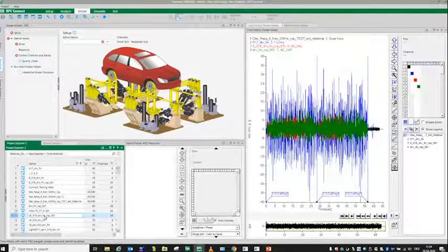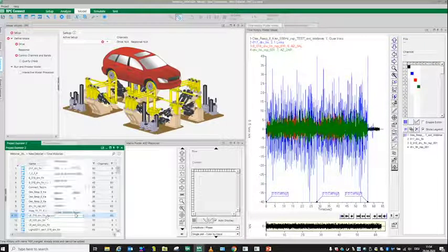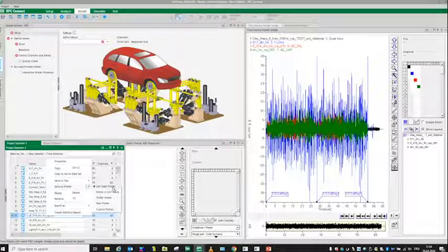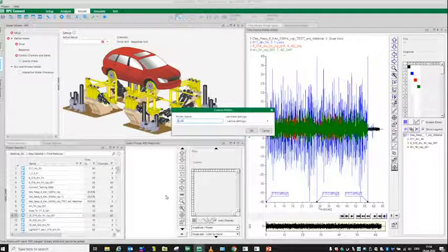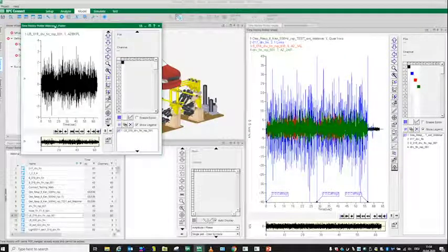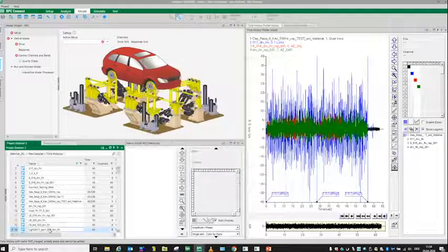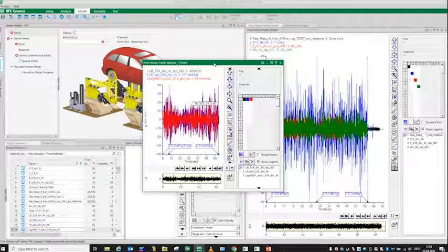Let's say I want to compare now 3 different files. Now I go to send to plotter. I can send to the active or last used plotter. I can send the plotter into editor mode, of course, to cut it, to set regions, whatever. I can go for a new plotter or, of course, a custom plotter. Let's say I call it webinar 1 plotter. Say, okay, use these settings. It will open a webinar 1 plotter here. The file is sent there, and the next double clicks will send the files to compare into that setting.